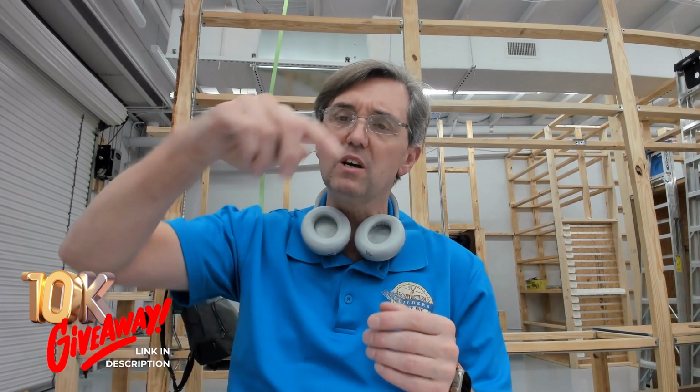And I'll show you a photo of it before we move on. So 3/4, I was basically cutting, let's just say for the sake of easy math, a 24-inch by 24-inch. Okay, they're a little bit less, but I came in from either end 2 inches, let's just say. So I'm cutting 22 by 22. I'm going 3/16 deep. Cut that toolpath.